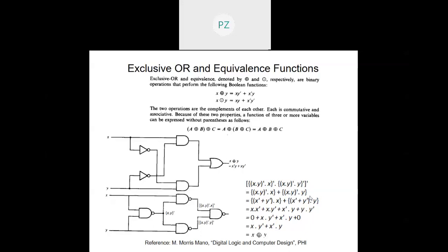So that is the first step of De Morgan's theorem. Let me go on applying De Morgan's theorem again. So now you must start feeling the importance of De Morgan's theorem. How important is De Morgan's theorem, right? In the next step, I'll open this one up. This will be (x' plus y') . x, which will be there anyway, right? Whereas on this side, it will be (x' plus y'). So when I open this one up, this AND will become OR, and each one of them will individually be complemented. So it will be (x' plus y') . y, right? So this will be the step from this one.